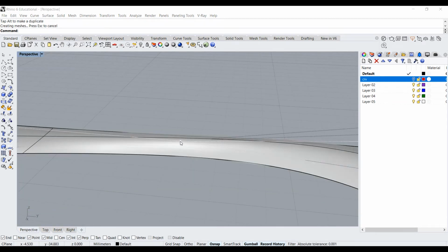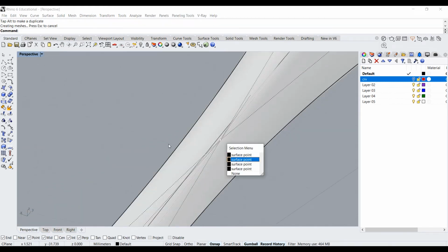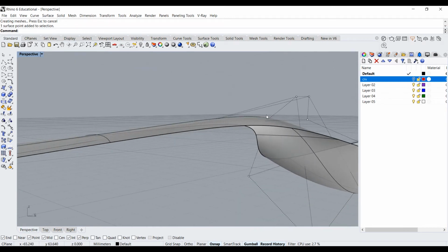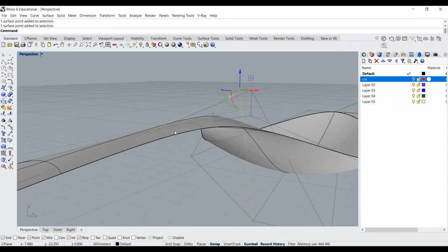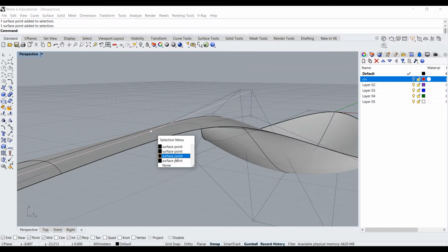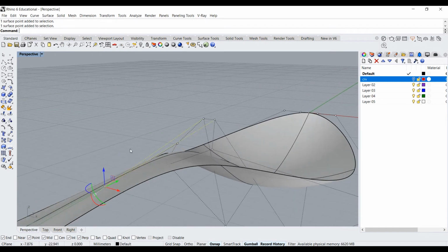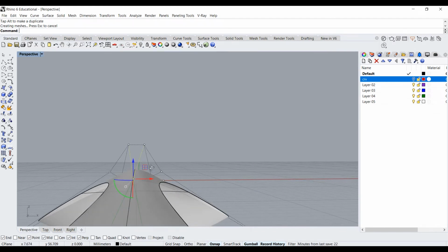And in the middle here, we want to grab the same middle points. But when we go to grab them or inspect them, you can see all 4 points are kind of stacked on top of each other, which is quite difficult to figure out what's what. So you'll notice when you click on a point, you get these yellow lines that show you the direction of where it's connected. So that means if I click and hold on this point, I can scroll up and down on the selection bar to select the ones we want. So we actually want this one here, and I'm going to hold down Shift and do the same, and this one here. So these are the 2 middle ones, because you see they're connected to those lines here, and I'm going to pull these up slightly. There we go, and that just helps me differentiate between the different points.